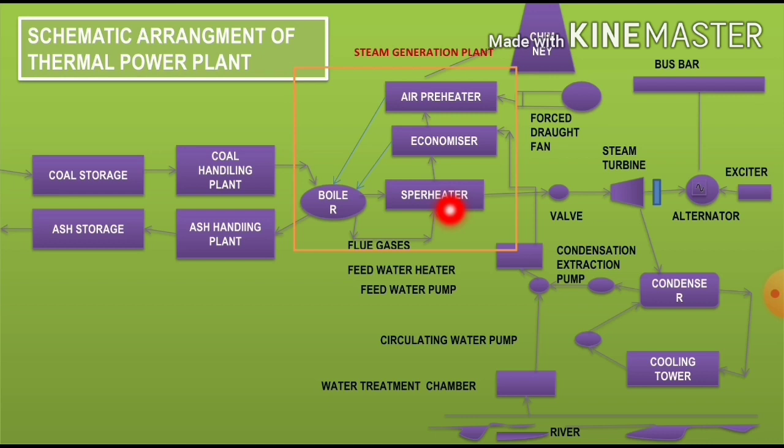The steam is superheated because by this we get two benefits. The overall efficiency increases. Too much condensation in the last stage of the turbine, which would cause blade corrosion, is avoided. The superheated steam from the superheater is fed to the steam turbine through the main valve.